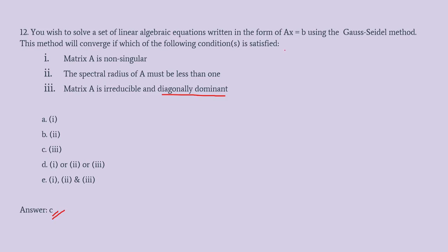For most of the CFD schemes or matrix solution schemes, the diagonal element should be present, and it should be diagonally dominant. This is a valid criterion for most of the matrix reduction techniques used in CFD.